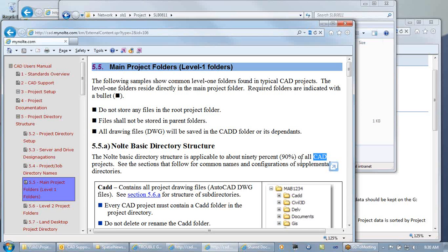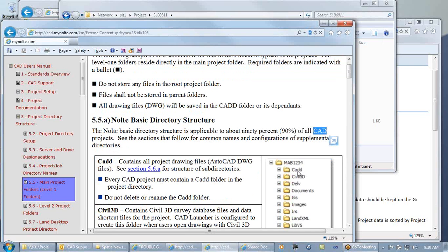So the folder is 2 Ds. When I write about it, I usually just use a single D, but I stress that because I do get people who will set up a project and type in CAD, and then several months from now they're going to wonder why it can't find any of their XREFs or why stuff isn't working.